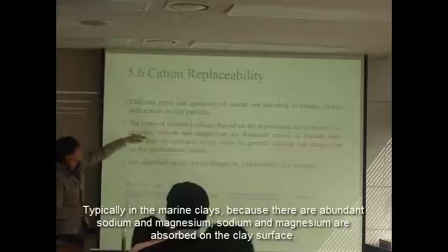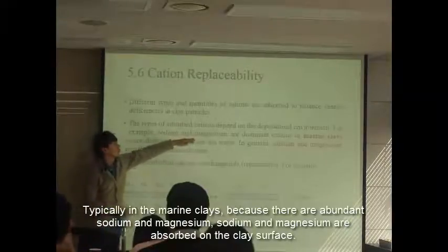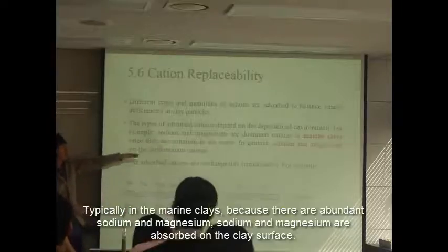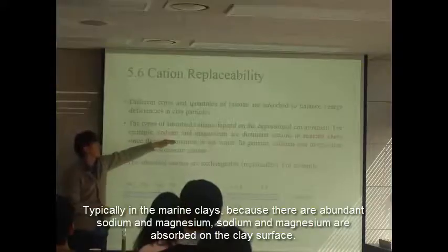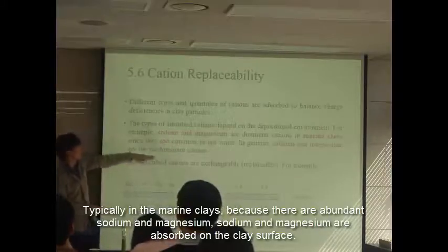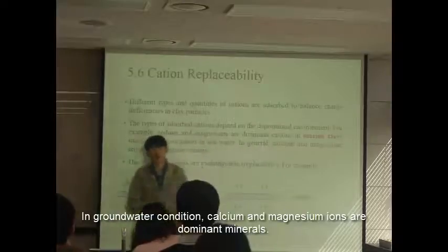Typically, in marine clay, because there is abundant sodium and magnesium, the clay surface is covered by adsorbed sodium and magnesium, while in groundwater conditions, calcium and magnesium are the dominant cations.